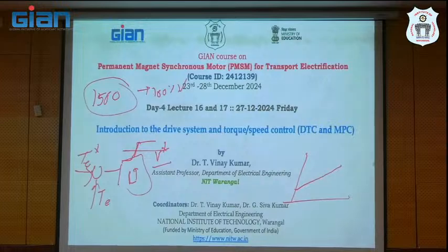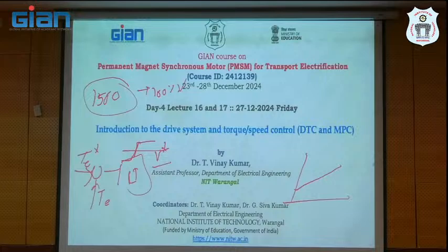To meet 500 RPM, the same voltage will not apply across the motor terminal. It will apply only 10% of the rated voltage to limit the current. Right? This is the current control concept for all electrical systems.